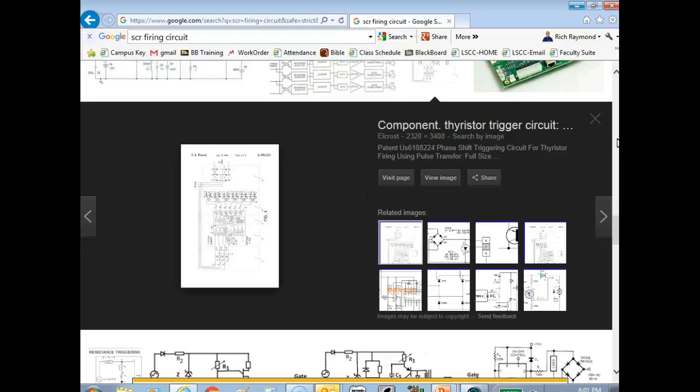Well, if you water cool them, then you have that little thing I showed y'all, right? The water cooled jackets. That would take the place of the SCR. I mean, take the place of the heat sink. And like I said, we had one unit out there that used water cooled jackets. All the rest of them were older, and they all used heat sinks. And you could tell the difference real fast.